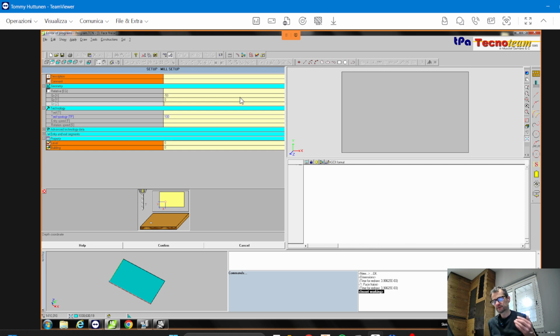So I don't go down. Minus, right. So you need minus, for example, 19 or 20. Maybe it's better 20, because we know the thickness of the panel is 19. If you put 20, you have 1 millimeter more than the thickness, so it's better for the cut. It's better because it's completely clean, and we are sure that we clean everything. So, right, minus 20 is a good answer.